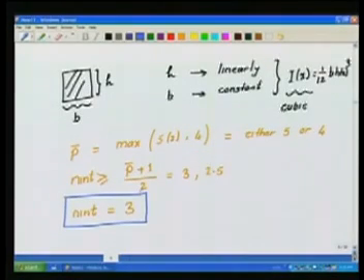So if we take the 3-point integration rule, we will get exact integrals as far as the stiffness part is concerned and as far as the load part is concerned. Okay. So remember that these are procedures which are now very similar to what we have done. So if I want to incorporate this in my finite element program, which I have already written, I do not have to change much. All I say, the preprocessor, you see that the mesh will be the same.